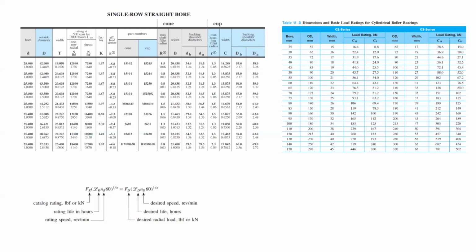You see an interesting example of this in F1. Instead of what we use, they use angular contact bearings as opposed to tapered roller. Angular contact in general can support smaller radial loads, smaller moment loads. Basically, it's worse for stiffness in most of these metrics, but yet F1 teams choose to use it. Why? Because they're operating at speeds that are maybe 4 to 5 times what we ever go. So their consideration of losses and fuel consumption are suddenly much more important than stiffness, right? So even in the same kinds of systems, this can manifest in really different ways. Obviously we could go to angular contact, but there's not as much of a benefit as an F1 car has. They're dealing with larger loads too, yet they choose to use this bearing because that one requirement is so important.